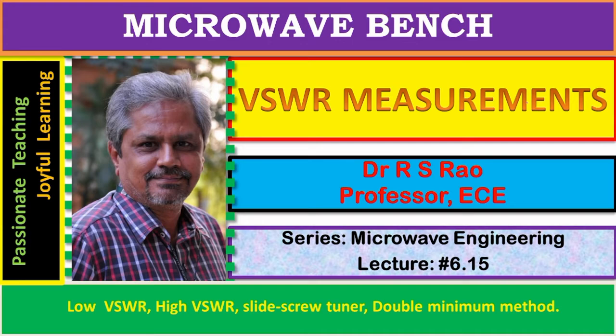It assumes 1 when the line is terminated in its characteristic impedance, that is, when a matched load is the termination, then SWR over the line becomes 1. SWR assumes huge values when the termination is either a short circuit or open circuit, or when it is a pure reactance. For other loads, the SWR value is between 1 and infinity.